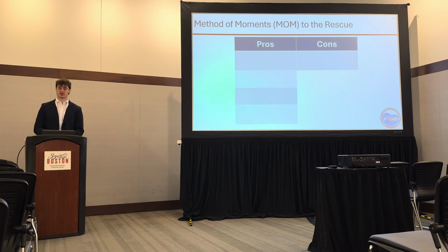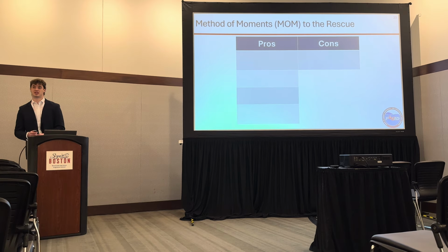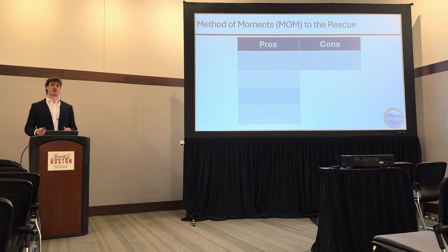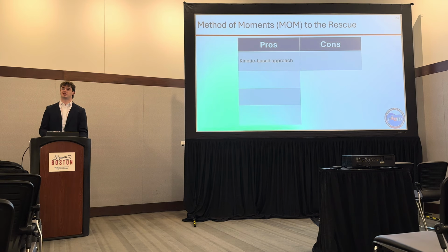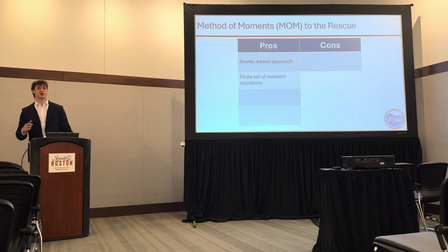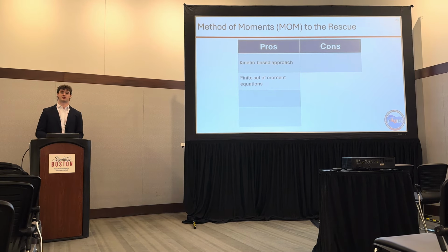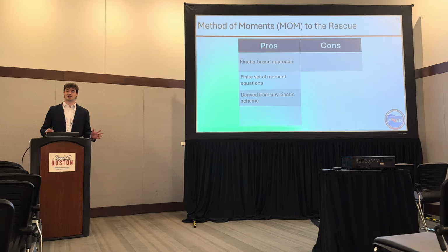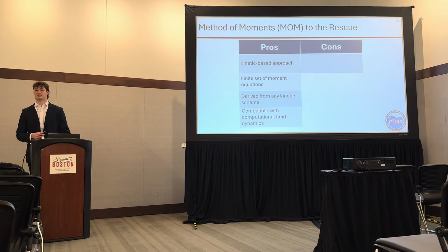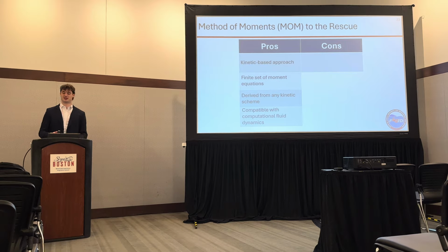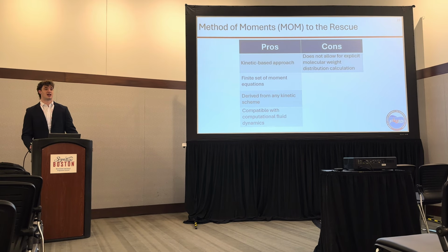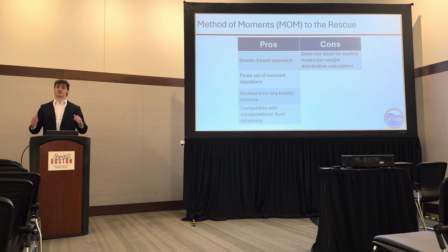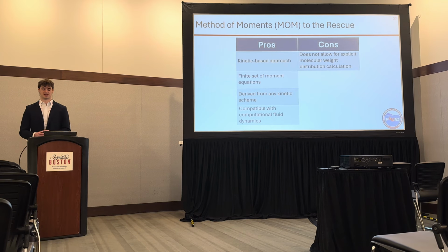Now that's where the method of moments comes in. I'll give you a little bit of information about this just to be dangerous, but my colleague will be presenting a little bit about this and molecular weight distribution reconstruction in this room around 12:30. So the method of moments is a kinetic-based approach that reduces your infinite set of partial differential equations down to a finite set of moment equations. The cool thing about the method of moments is it can be derived with any kinetic scheme, not just polymerization, and it's compatible with CFD, which is obviously a big thing if we're using CFD. The only issue is that it does not allow for the explicit calculation of the molecular weight distribution, which again, is not a concern for this research exactly, but my colleague will be presenting on that later today.